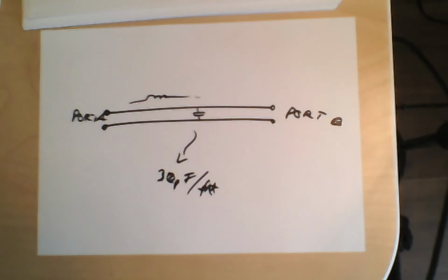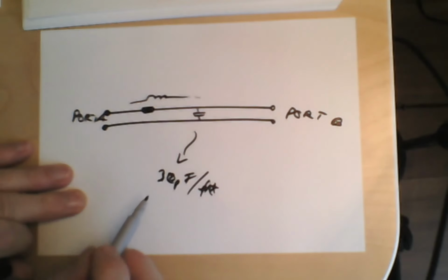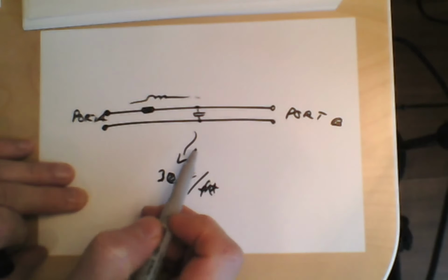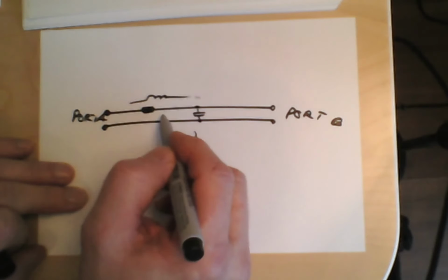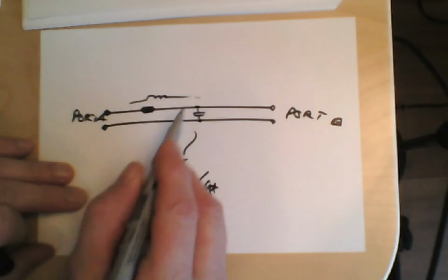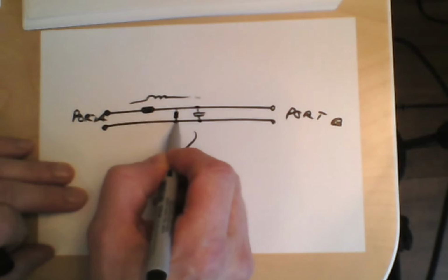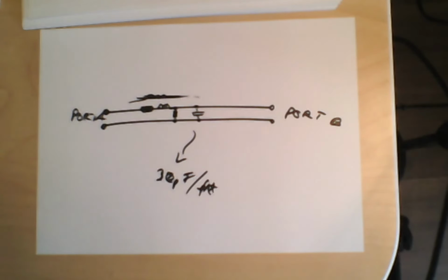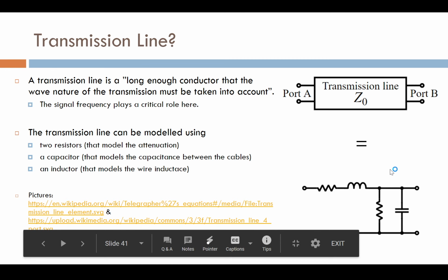So basically then on these wires you have serial resistance. In addition to that, you will have some power loss. When you are applying voltage here, there's a power loss on this cable because the insulator is leaking a bit. So basically it also has this loss resistor in between. Okay, that inductor actually is part of the wire. So that's why the model of any long transmission line looks like that.